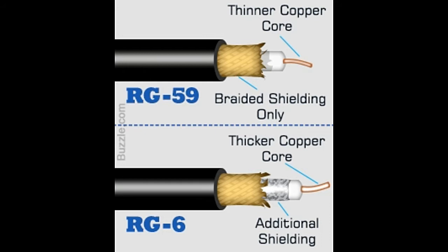All coaxial cables are constructed with a steel, copper, or aluminum conductor core, which is surrounded by a layer of white/black dielectric insulation. This is further covered with a tube-like braid of copper wires, which is wrapped around by a solid polyvinyl chloride insulating cover called a jacket. Some coaxial cables may have a layer of foil between the dielectric and the conducting core.